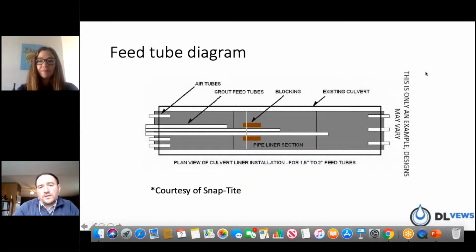So that's one critical thing that I don't think we've touched on yet today. If you have a pipe that's 10% pitch, let's call it 20% pitch for extreme, versus a pipe that's flat, maybe 1 or 2%, those two pipes are going to grout a lot differently. You'll get a nice equal distribution on the bottom of a flatter pipe, but if you've got a pipe that's pitched quite well, all your grout's going to want to float to the bottom. So that liquid pressure on that pipe has to be considered, and the bulkhead for that matter.